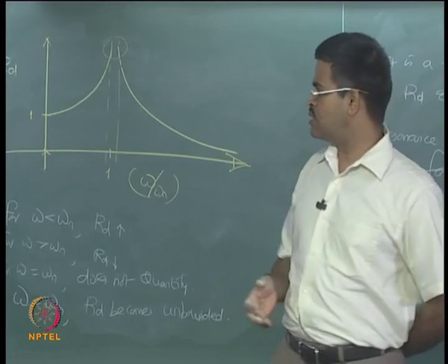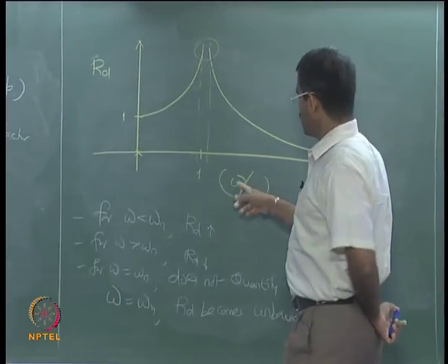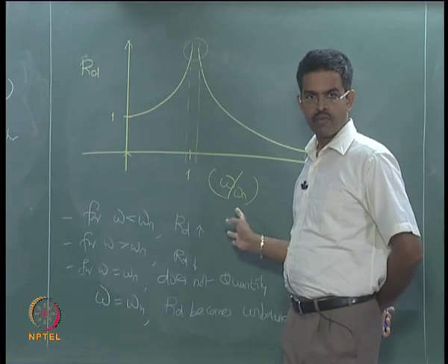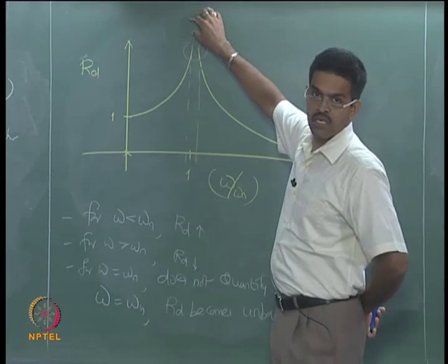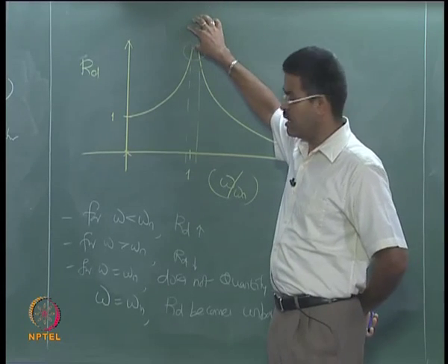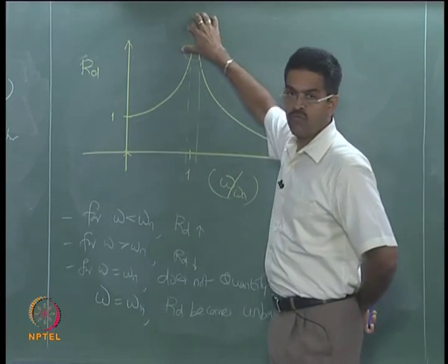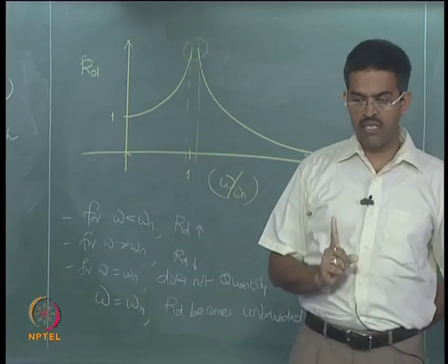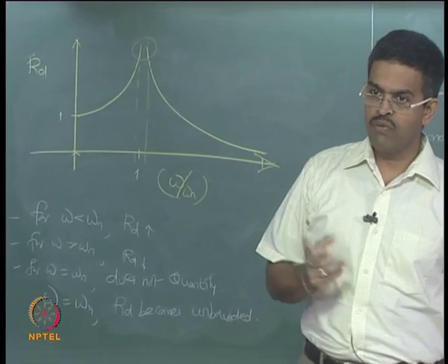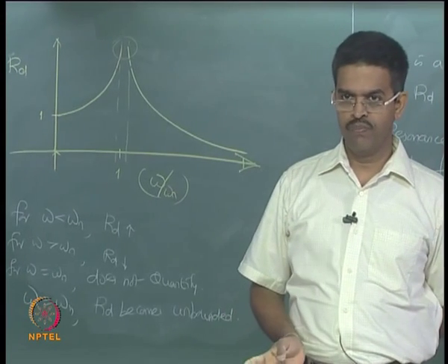We also understood at this band, since these two frequencies match, it is seen that it is unbounded, which gives an alarming signal to any engineering person, saying at resonance will my platform fail, because the response factor shoots up to infinity or an unbounded value.